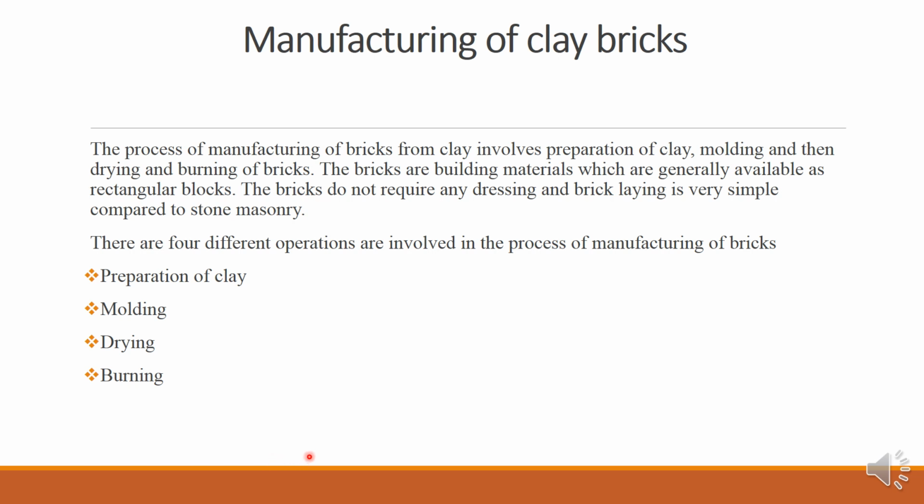If they are burned beyond the limit, they will become brittle and break easily. If they are burned under this limit, they will not gain full strength and there is a chance they absorb moisture from the atmosphere. Hence, burning should be done properly to meet the requirements of a good brick.